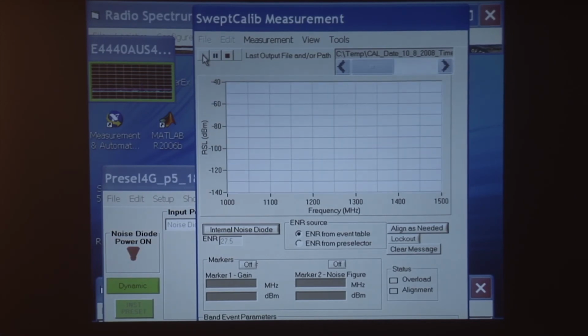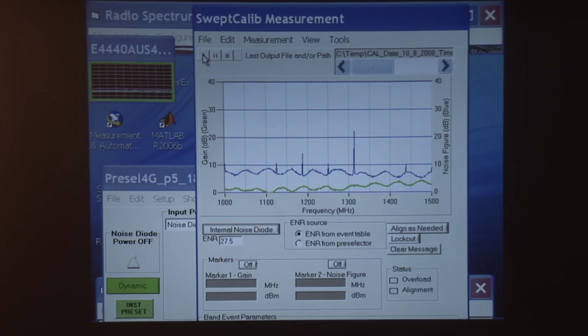The reason I know that is on a spectrum analyzer, when we put in 30 dB of attenuation, I watched to make sure that I stopped when the output of the amplifier coming through the attenuator was about 3 dB above the noise floor of the spectrum analyzer. Meaning that when we turned the amplifier on and off, the power coming out of the amplifier was about equal to the spectrum analyzer's noise floor. Here we've now gone 6 dB beyond that.